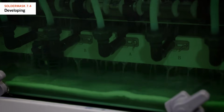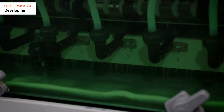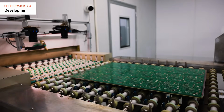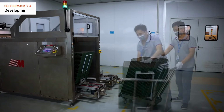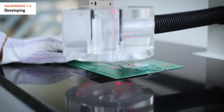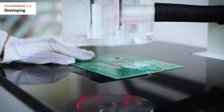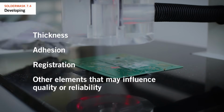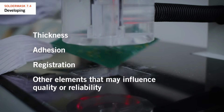While the process ends with rinsing to remove any chemical residues followed by a final drying of the panel, there is typically an in-process quality control step directly after, where the deposit of solder mask is checked, considering thickness, adhesion, registration, and other elements that may influence quality or reliability.